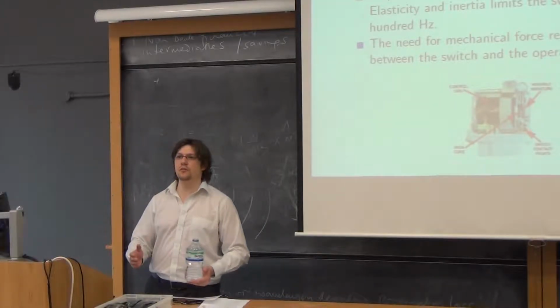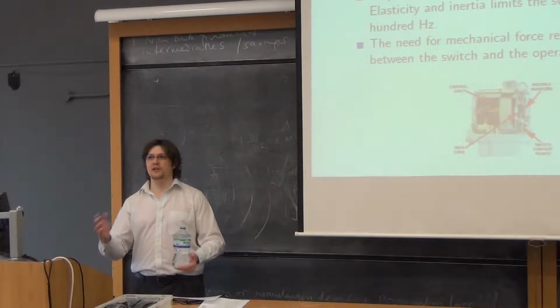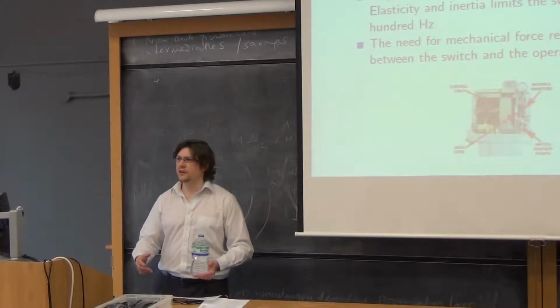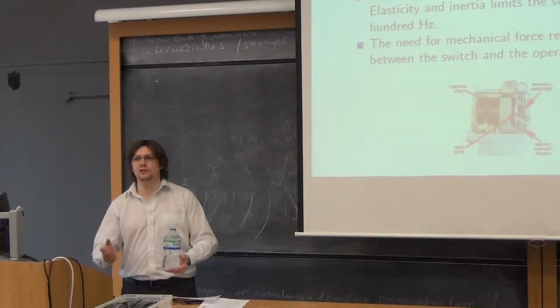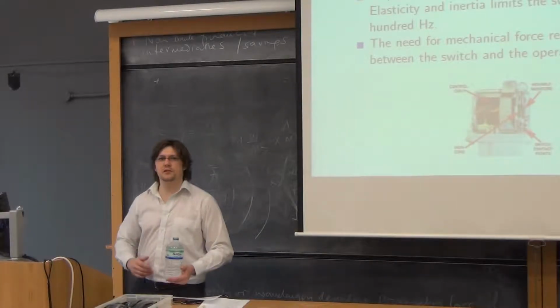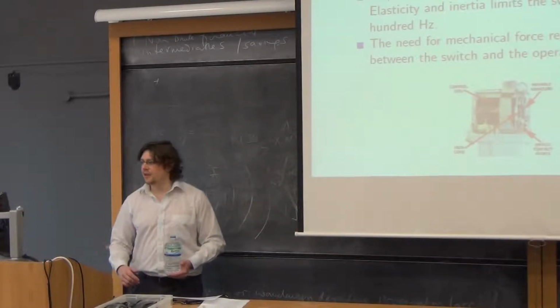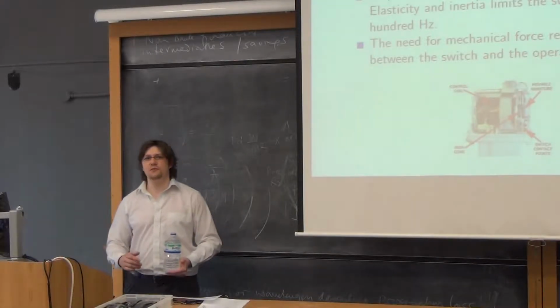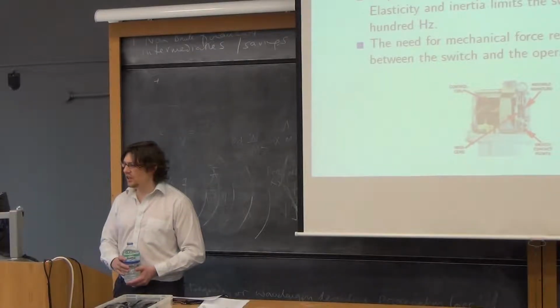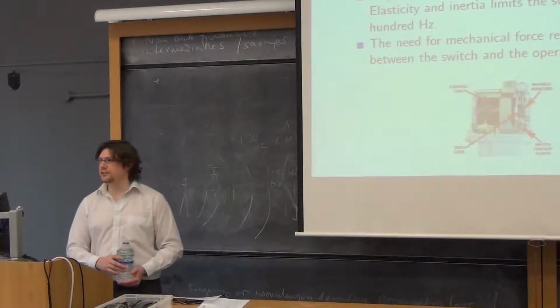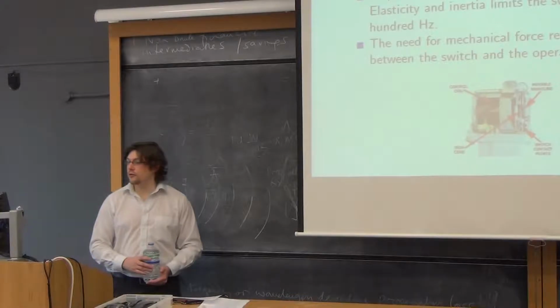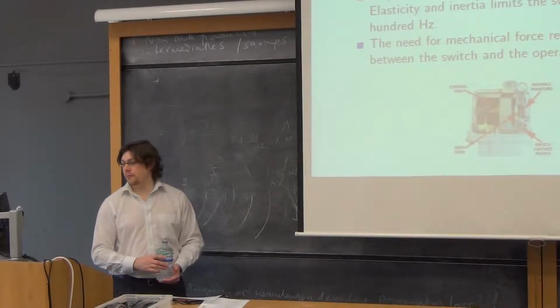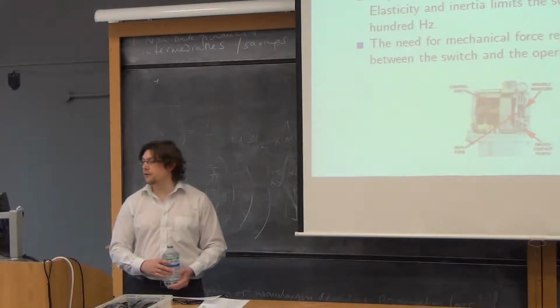Also, breaking an enormous current requires quite a big distance, and you have to do cool things like fill the switch with oil to make sure the arc is quenched. But that's really power distribution stuff, and I don't want to get into it. But a milliamp to 10 megaamps, relatively easy. So they have very low contact resistance and very low leakage. That's to say, RP is very high and RS is extremely low.